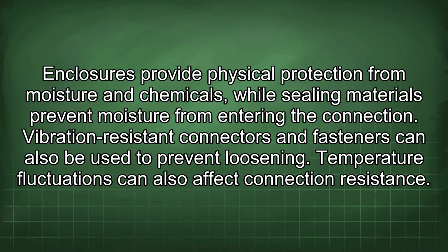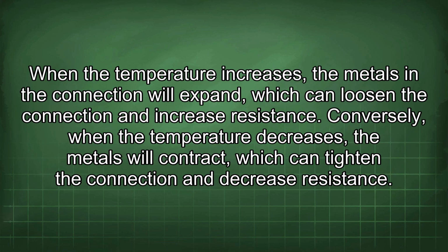Temperature fluctuations can also affect connection resistance. When the temperature increases, the metals in the connection will expand, which can loosen the connection and increase resistance. Conversely, when the temperature decreases, the metals will contract, which can tighten the connection and decrease resistance.